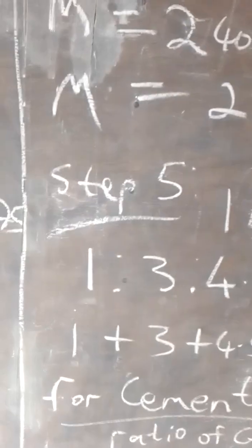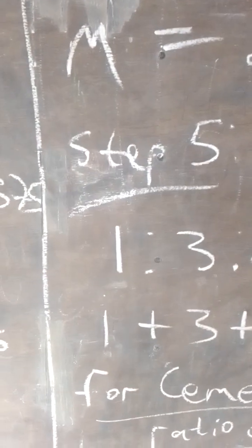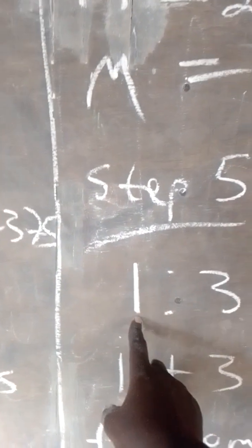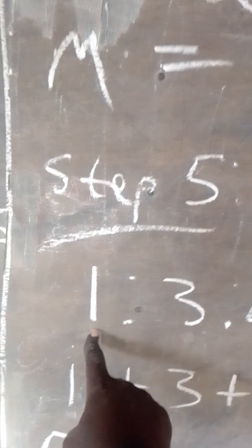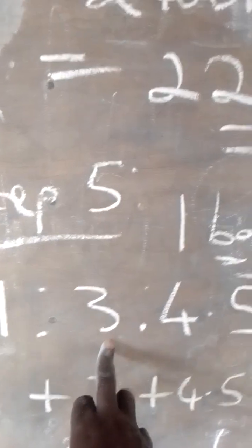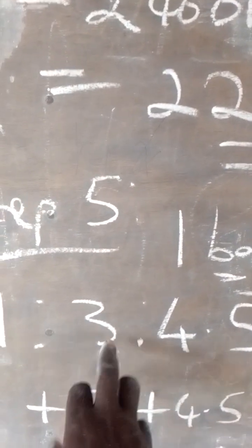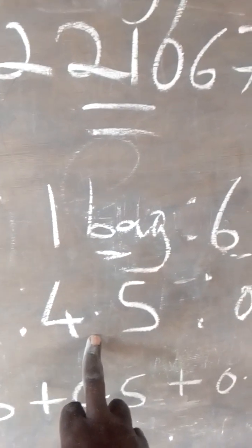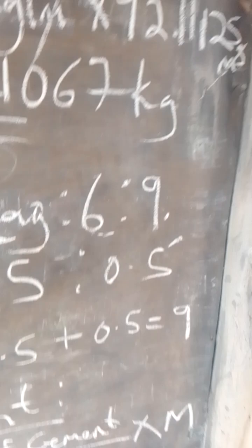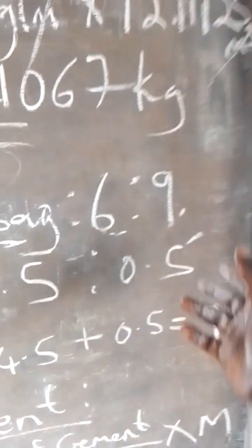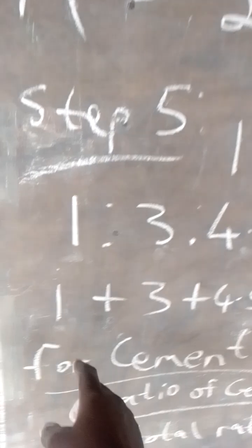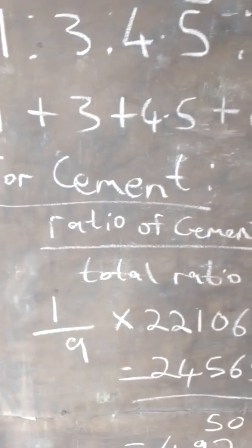Water cannot heap up, it's only sand that can heap up. So half headpan is the water level of sand, and the water level of chippings is 4.5, that is half of the 9. That's what we use in calculation. I always use 0.5 as the water cement ratio. So add the ratio together. This is what we did here. I'm trying to give you a little.